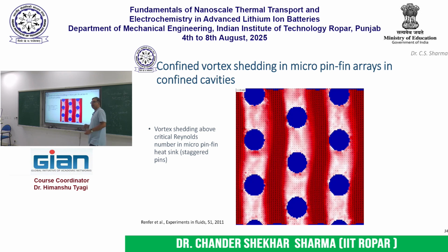Yes, in that case the vortex shedding will be more, but the pressure drop will also be high. So then you have to take a call in terms of the trade-off: for the increased pressure drop penalty, are you getting a higher increase in the heat transfer?